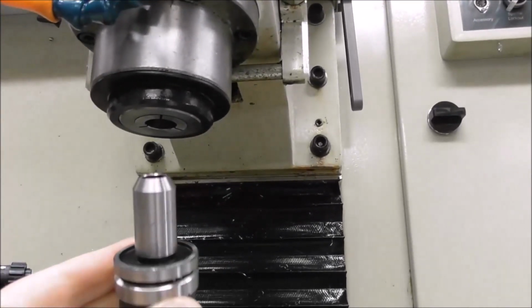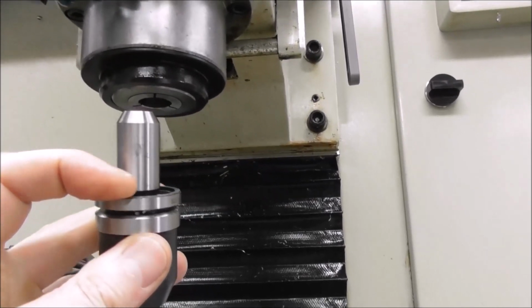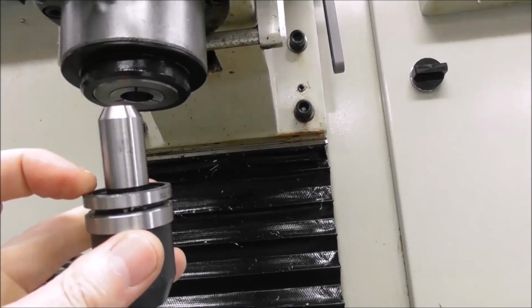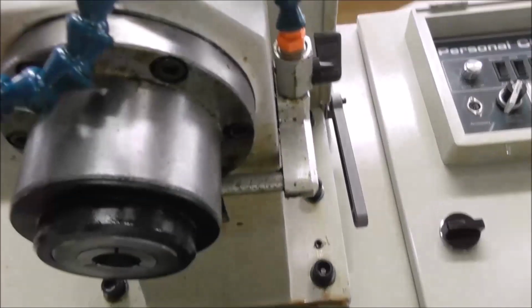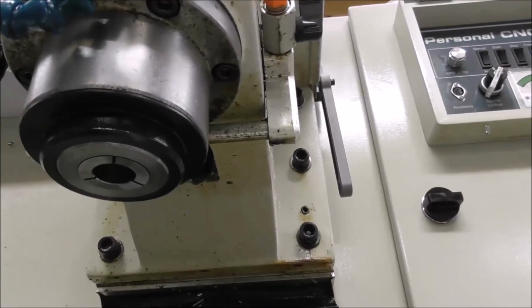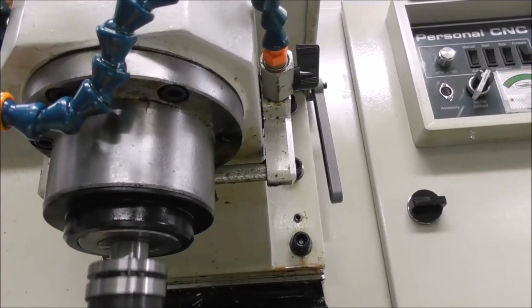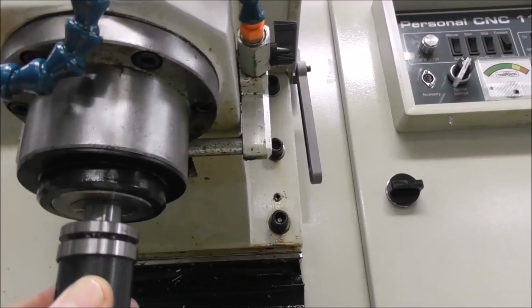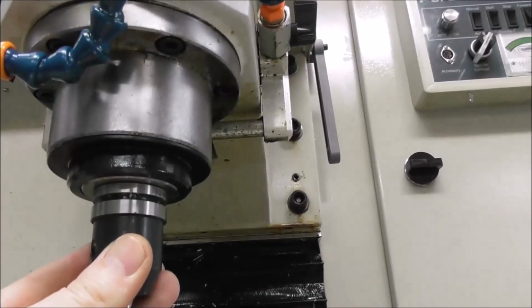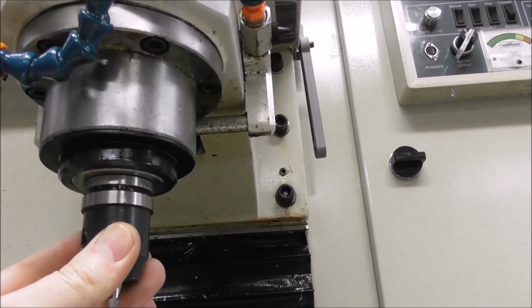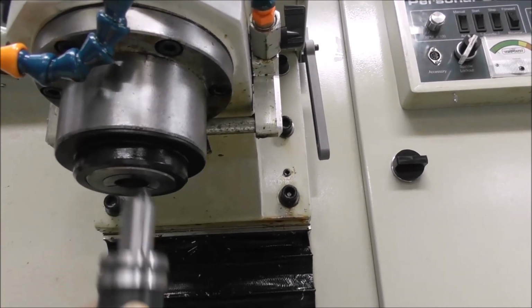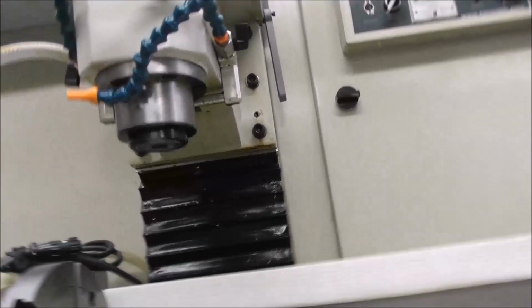Of course, the way TTS operates is that the surface on the flange of the TTS contacts the underside of the spindle nose, so that you get a repeatable Z position, that it pulls up firmly on the end of the spindle nose in an accurate position. But of course in reality it's not quite that simple.